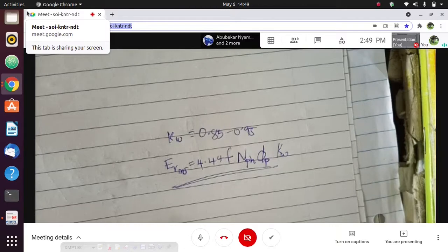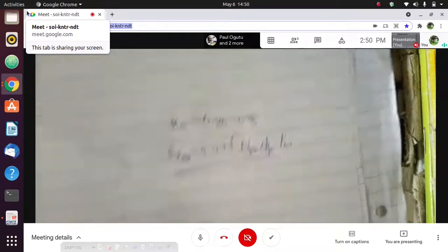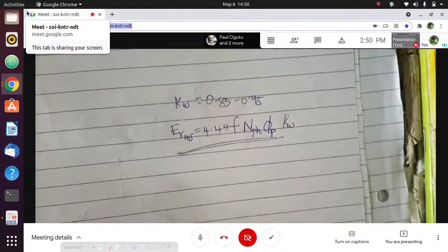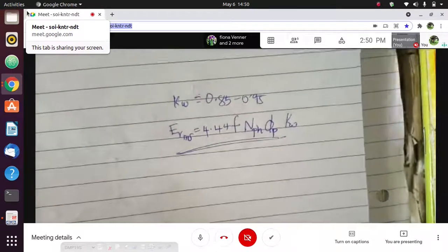If the three-phase windings are connected to a three-phase supply, then a rotating magnetic field will be produced in the air gap. But since the rotor is not connected to a circuit, it is open circuited. That means that rotating magnetic field cannot drive current in the rotor circuit. That rotating magnetic field will be rotating at synchronous speed.